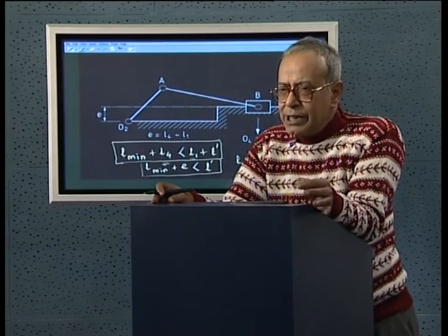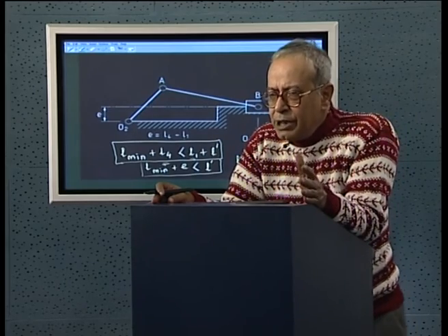So, to conclude today's lecture, we have seen that the rotatability of a 4R linkage is most comprehensively summarized by what we call Grashof's criterion. When we apply it to a 4R linkage, L min plus L max less than L prime plus L double prime satisfies the Grashof's criteria, and from a Grashof linkage, by kinematic inversion, we can get all kinds of linkages. Then we have seen the motion characteristics of non-Grashof linkages, that is, when Grashof's condition is violated. We have also seen the boundary between Grashof and non-Grashof linkages, which we call transition linkages, and then the special cases of transition linkages, where the chain consists of two pairs of equal link lengths.